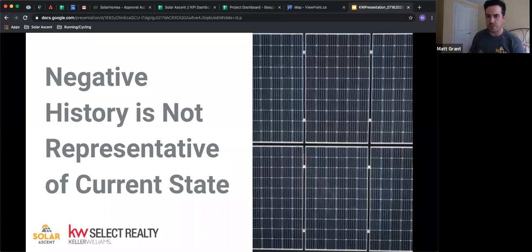Again, that goes installer to installer. But the design kits for the installations are really solid. There's great solutions for metal roofs and great solutions for asphalt roofs. In terms of roof age, if something's in really good shape and it's around 7 years old, we'll install on it. If it's getting above 7 years, we'll probably recommend the homeowner do a roof before solar.